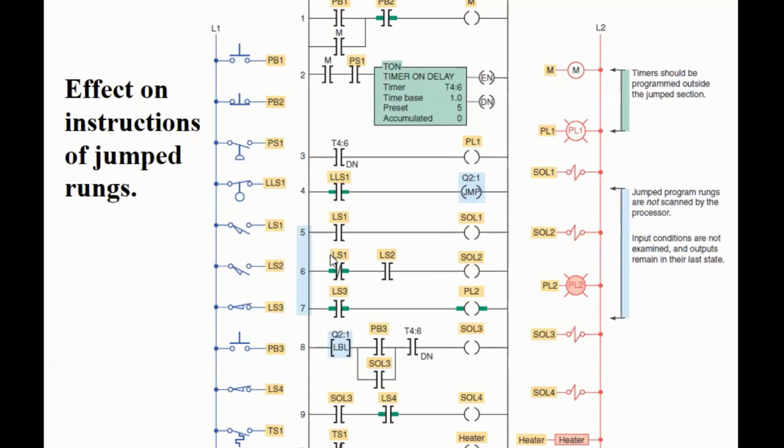What's the purpose of jump instructions, you may ask? Well, if you have a certain multitask ladder project and the conditions are such that you don't have to run the first 10 rungs, then you can have a jump instruction that will go to rung 11 and run rungs 11 through 15 instead, right? Because otherwise time would be consumed checking rungs 1 through 10 without needing to, and instead you can directly jump over to rung 11. So jump is jump. That's the idea of it.